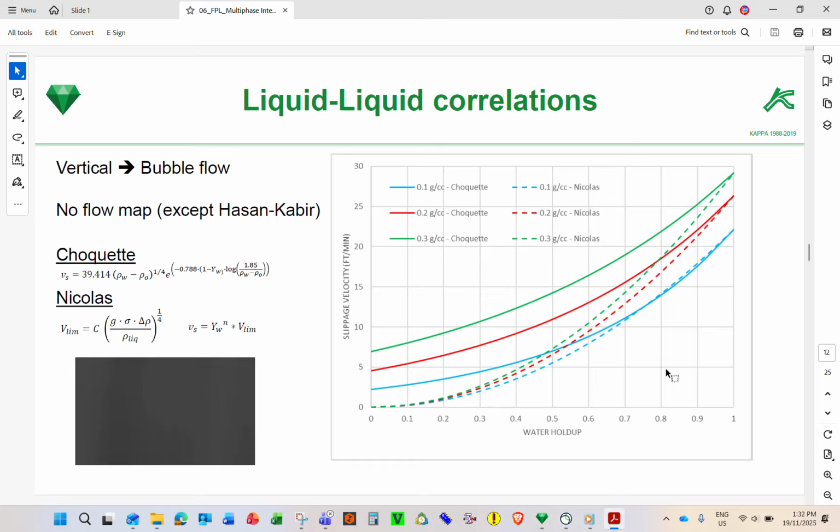Yeah, if you run the downhole camera, you can actually see this one. But the liquid needs to be very clear, like water. If it is mixed, you cannot see. If you see a lot of bubbles like that, once you know the size of the bubble and the number of bubbles, you can calculate the Q without the spinner.